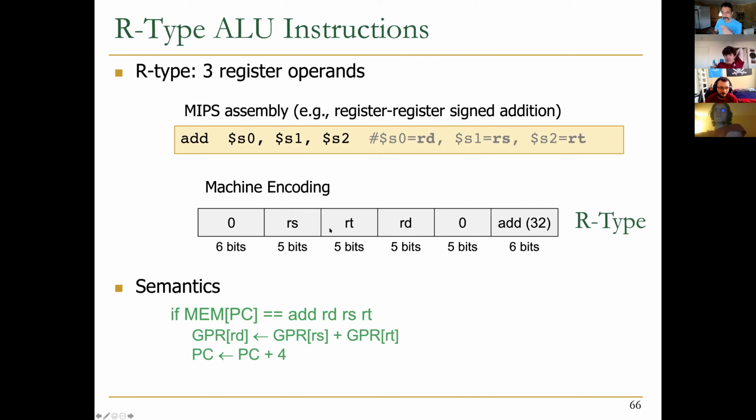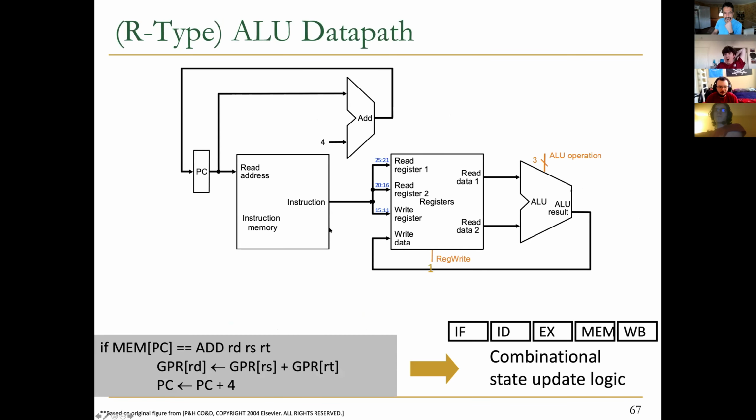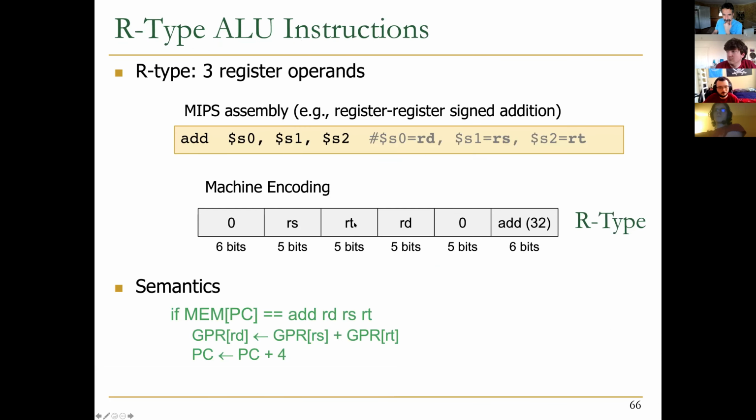Because you need to know this once you retrieve it. So here, you retrieve 32 bits, okay? Here you have exactly 32 bits. Then you need to know the two registers that you need to add together. So bits 16 to 20 and 21 to 25 are the two source registers that you need to add together, right? So again, these encodings, these two 5 bits, okay? So hopefully this is clear.